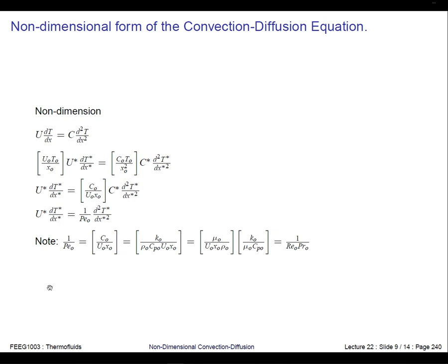Okay, and we can do a little bit more with the Peclet number. So that's what the Peclet number is, which we got from above, and we can put in what C0 actually was. If you remember from earlier on, it's the thermal conductivity divided by the density divided by the specific heat. And then we can multiply and divide by viscosity here. So here's viscosity on the top and here's viscosity on the bottom, and we can group these things together in slightly different ways.